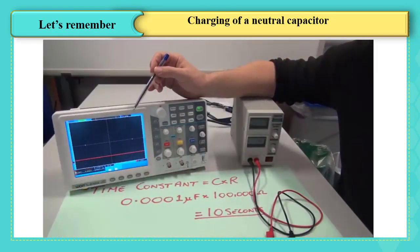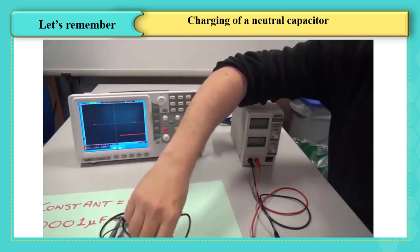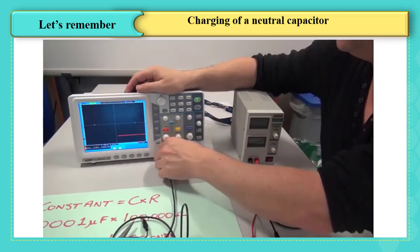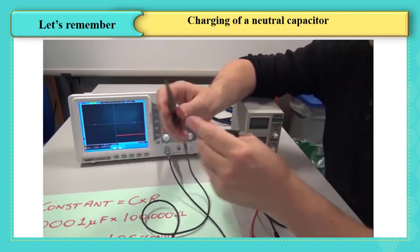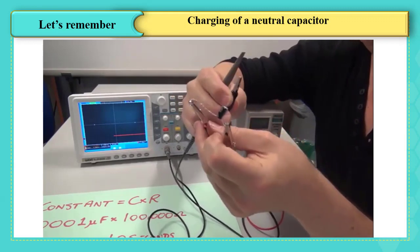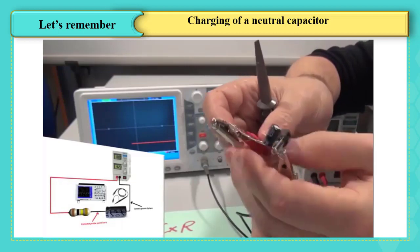And here we have the oscilloscope, and we're going to use the oscilloscope to measure the voltage across the capacitor. We need to connect the scope. We have two ports here, channel 1, channel 2. It's simply push and twist. The probe itself has a ground clip, and that will connect to the ground of your circuit. Just like that.